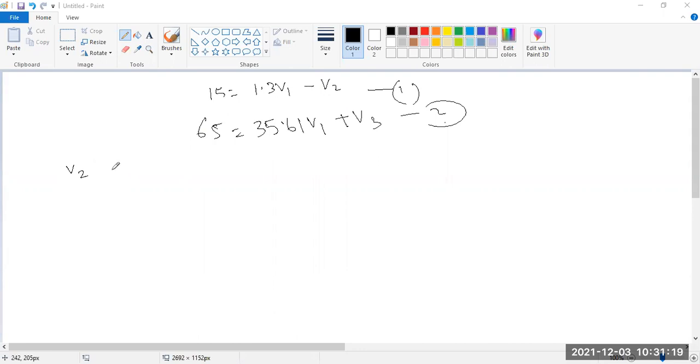That is your first equation, then the second nodal analysis. Remember the second equation was the initial point. Look, in your second node, there is another equation: V2 minus V1 divided by 3 plus V2 by 5 plus V2 minus 10 divided by 1 equal to 0. It was the second node.